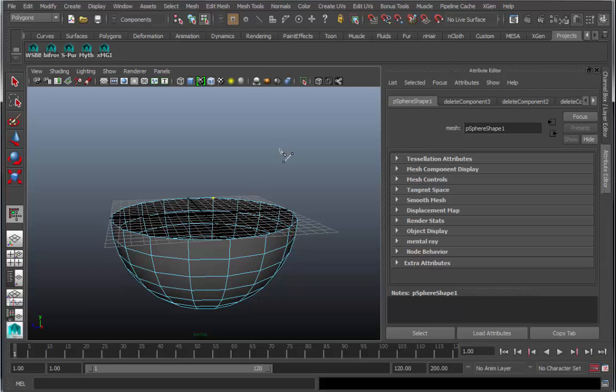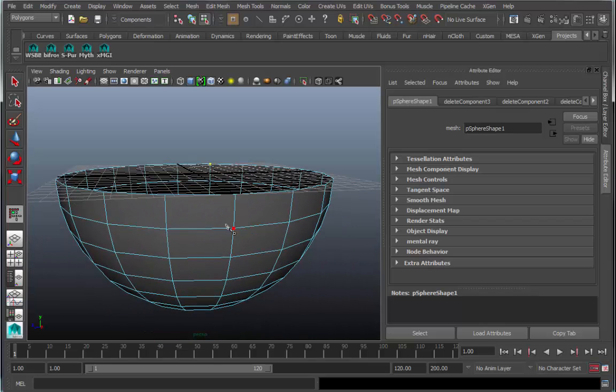And when you bring that up, your icon should change, this strange little X-Acto knife. And what we're going to be doing is, if you just trail your mouse along these edges, it tries to second guess where you're going to begin. And it allows you to click on an edge, then drag over, click on another edge, and continue until you're done. Then you press the Enter button, and it will accept that geometry.